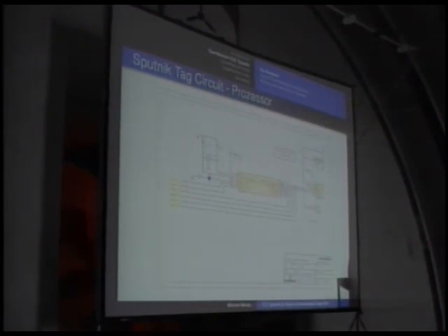Oh, that's also an interesting part. There is also a new change in the tag design. You can choose between two operating modes. For the current use, you obviously want to constantly power the tag, because it automatically sends data out. But if you move the 0 ohm resistors to this, there is a mode A1 and a mode B1. If you only connect this resistor, then you can turn on the tag with a push button.